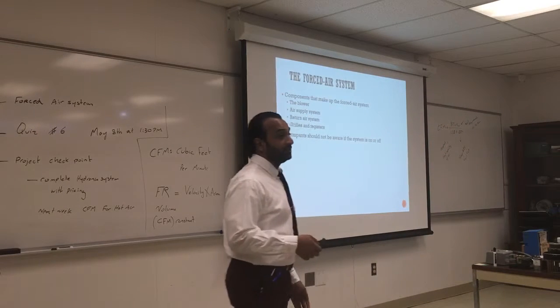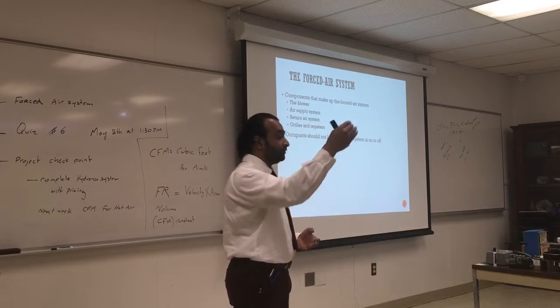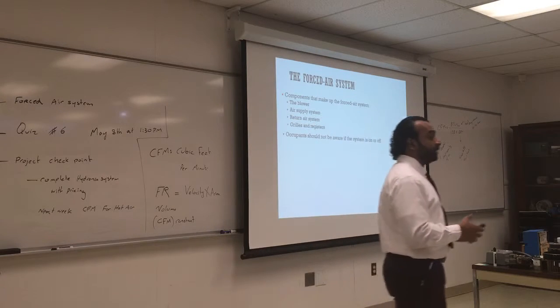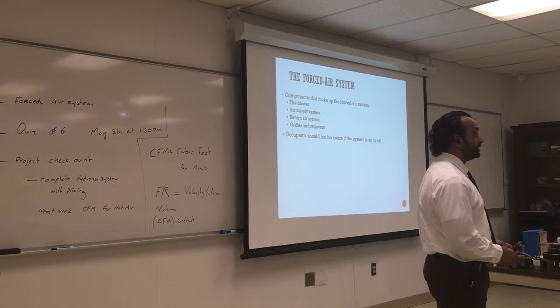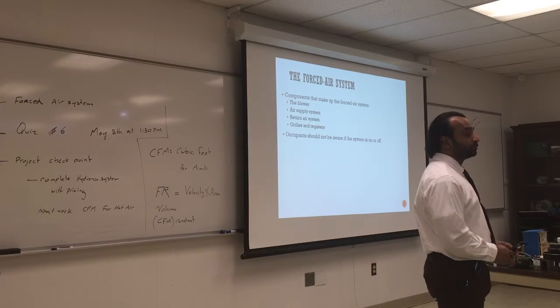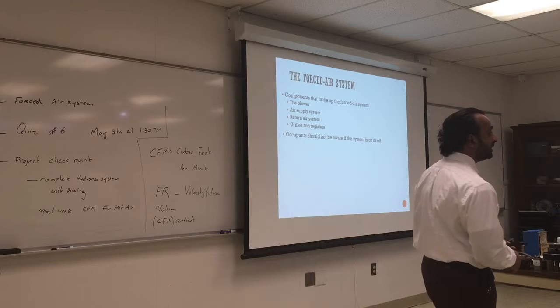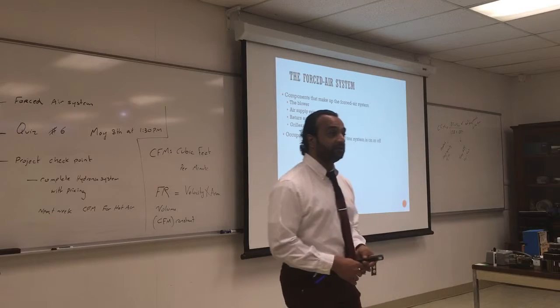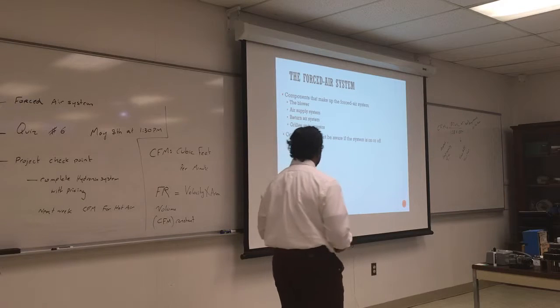Ideally, you want to have two returns, one for the hot and one for the cold, to have more even distribution, and you don't have to pump in air like crazy inside the house. But people try to minimize duct cost because the cost of duct is high, installation, design, and they sometimes have to be made in a warehouse and brought to the place and assembled there, so it costs a lot of money.